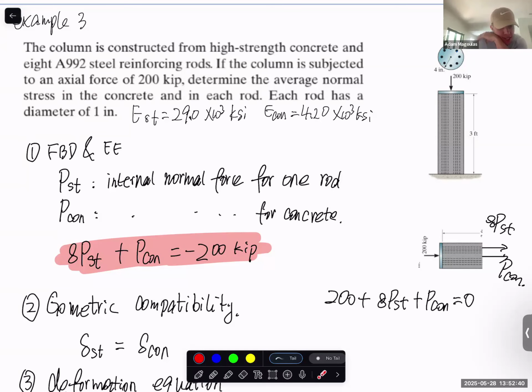For the second way you just said, where we draw the free body diagram, yes. I'm just confused on in that method why you initially chose the internal normal forces to be to the right. Do you remember the sign convention in the first class we talked about in statics? Static review. Oh, okay. Oh, because you cut the structure in half. How do you find the internal force? Let me ask you, how to find internal force? You cut a random point through the structure, and then you get internal force.